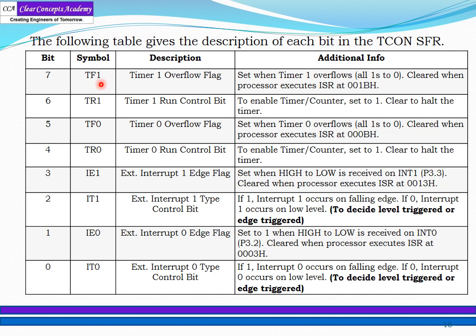When the timer occurs, then this TF1 will be set. That means it will show that the interrupt has occurred and it will jump to the address 001BH where the interrupt service routine has to be written.